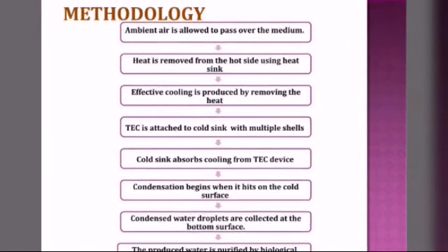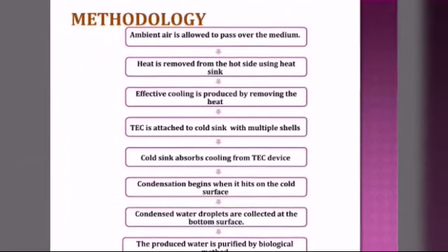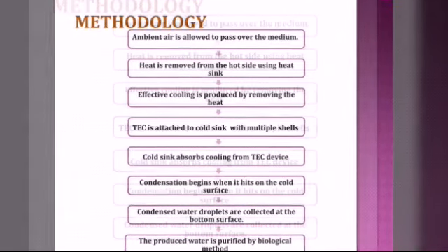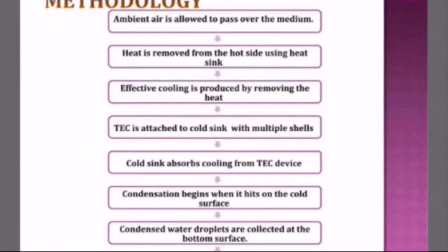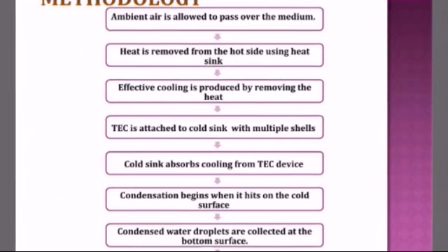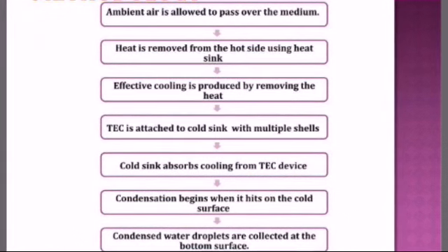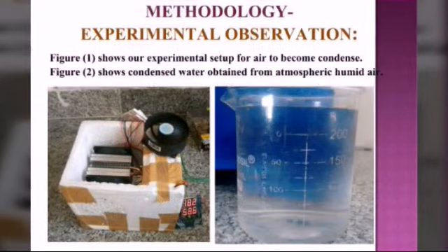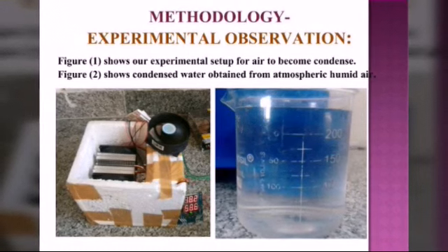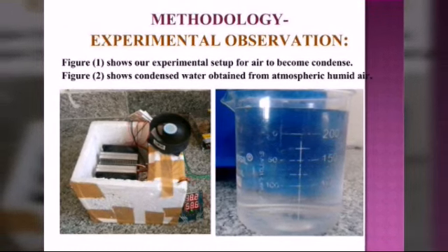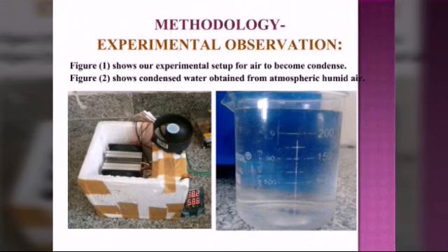Here we have the thermostats which show the relative humidity and the temperature of the surroundings and the inside. Here we are separating the heat and cold side because we have to develop the maximum cooling efficiency, that is, we separate the heat and cooling. Here it shows the relative humidity. Relative humidity is important for the dew point to occur and for the amount of water produced.